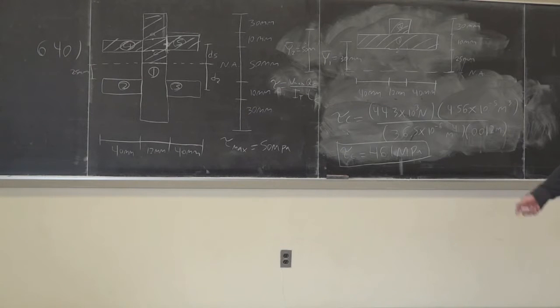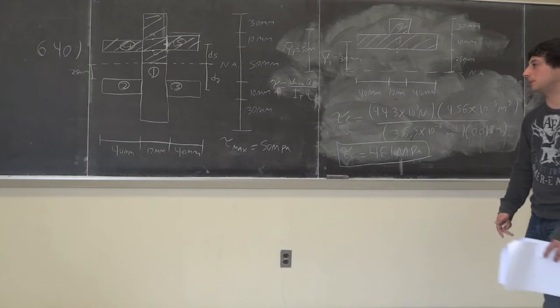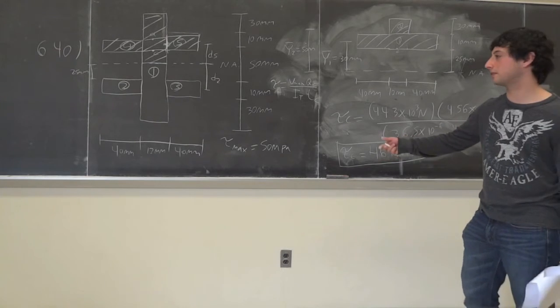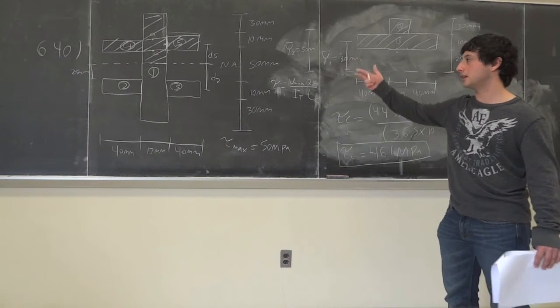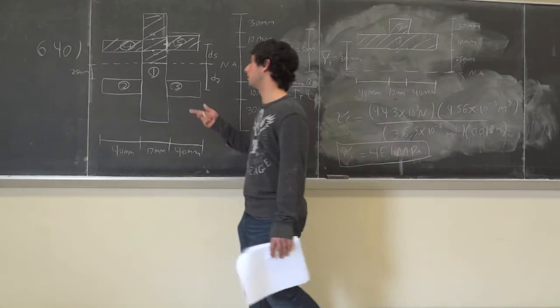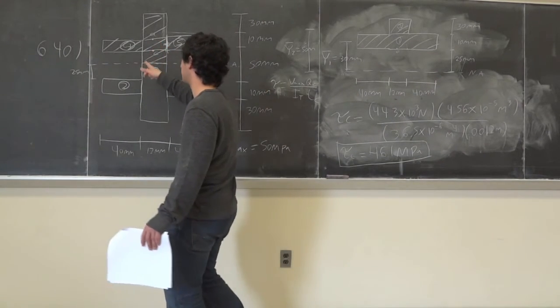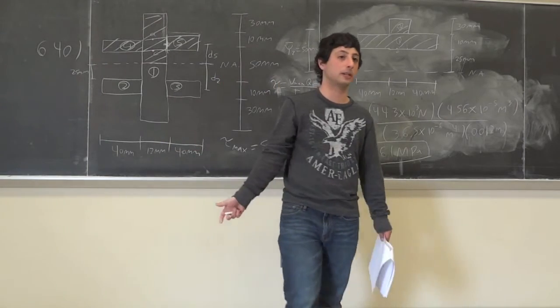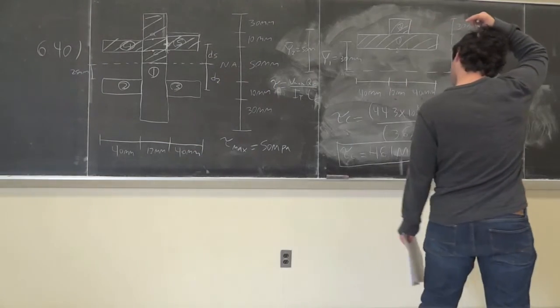You find the total moment of inertia, you find V. But people wouldn't even know what to do. You have to find V first, the shear force, in order to solve for the transverse shear in these sections. So that would be the most points, something like that. Okay.